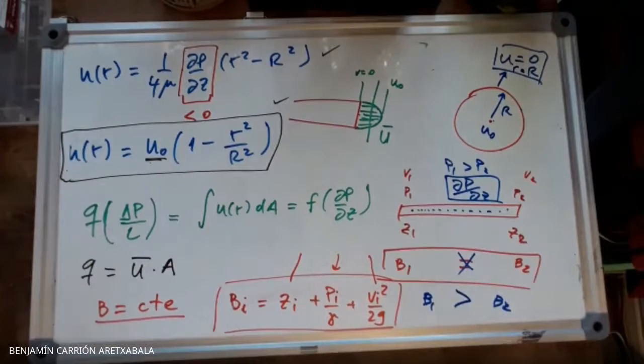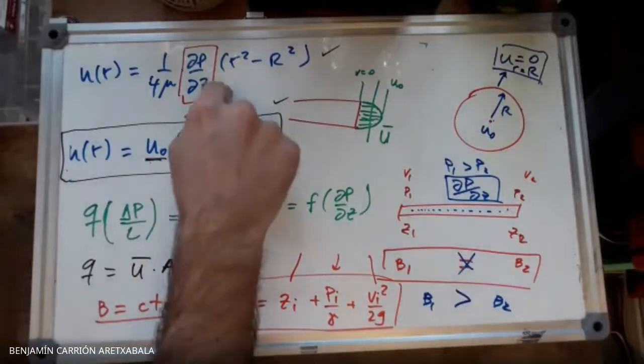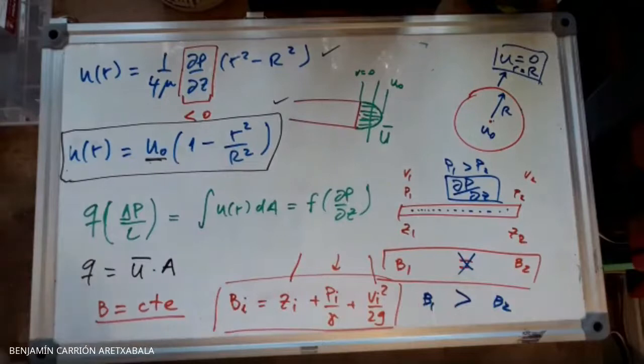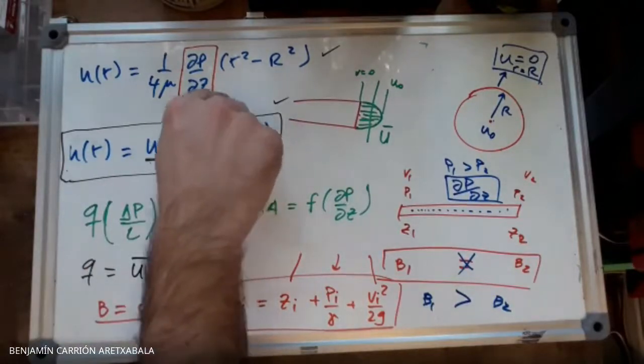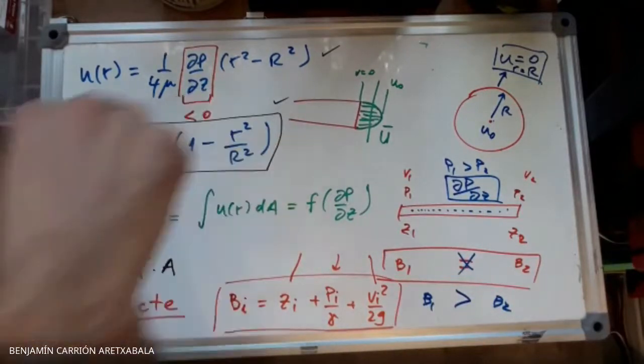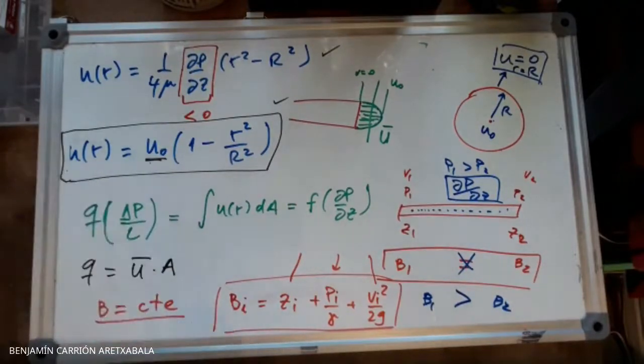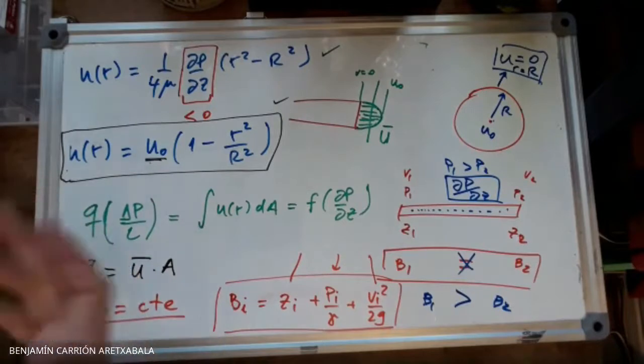There are ways to compute this drop in energy because of friction, that we're not going to go into in detail now, but we could compute how the pressure is dropping because of the friction. And this is where it gets complicated, because as you can imagine, this depends on the velocity. The larger the velocity, the larger the pressure drop.